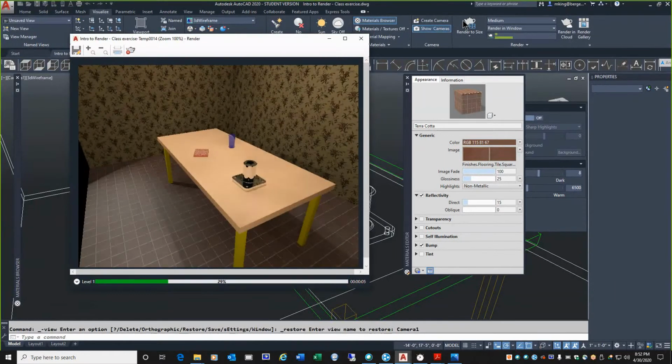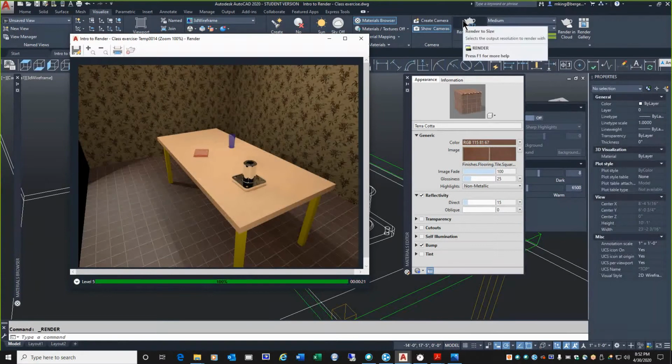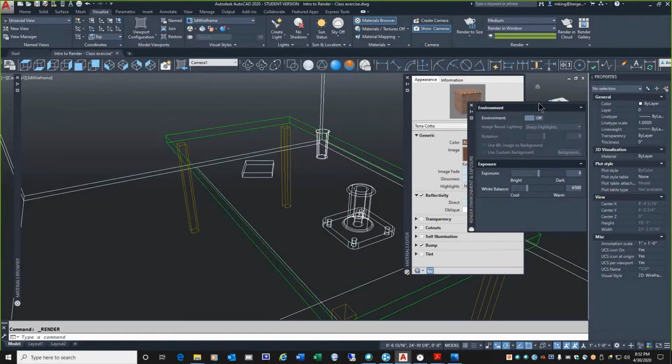Not remarkably brighter. So I wanted to do that first, and then we're going to go with the exposure control a bit more. The other thing we have is the lights have intensities. It's like changing a 60-watt bulb with a 100-watt bulb. We could click on the light and in the properties up the intensity. The default will be 1. We could try 1 1/4, 1 1/2. But I think we're going to just lower the environment exposure a little bit.